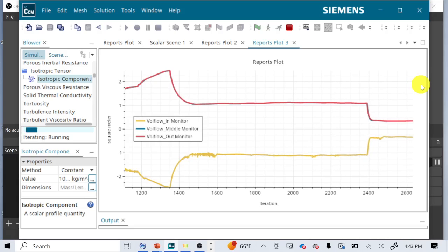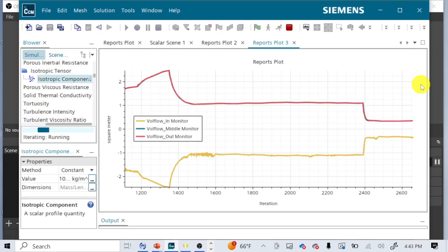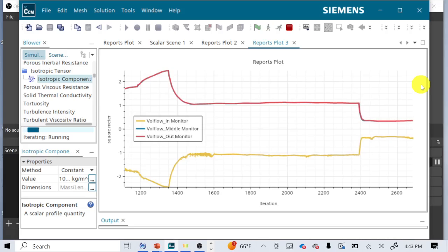If we have a 0 resistance, clearly we're going to have something with a 0 delta P. So we can definitely get 2 points. You can definitely bookend it on either end by cranking I to a very high value and seeing, it won't quite be here, but it might be like here. Something very close to volumetric flow rate equals 0, and something very close to the full flow volumetric flow rate. And then we want to get enough detail in the middle so we have an idea of what this curve looks like. What I don't want to see is you have 6 points that are all like right there. That doesn't tell us very much, because we have no idea what happens over there if you do that.